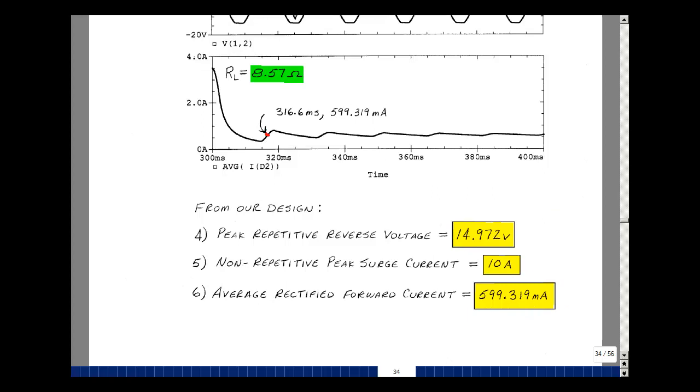One last comment, even though our DC output voltage at full load is only 10.378 volts instead of 12 volts, the power supply will still work because of the voltage range of partially discharged D-cell batteries. Dropping to 10.378 volts means it will have less power out. However, my true concern about this design is the large capacitor that we need for C sub L. In Supplemental Problem 3.19, we'll revisit this design and address this. And this is Supplemental Problem 2.15.